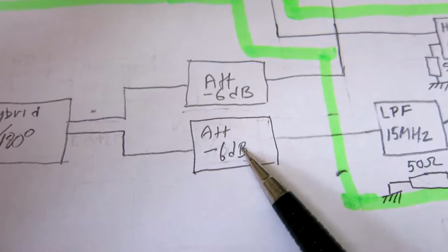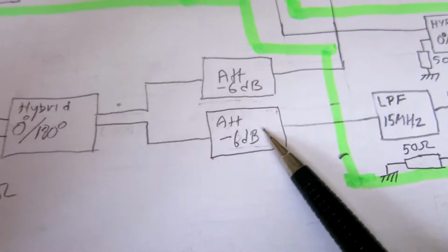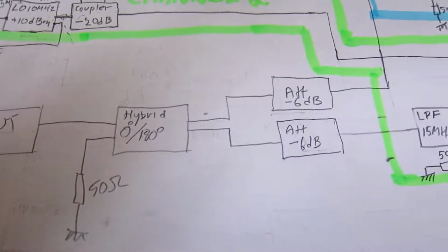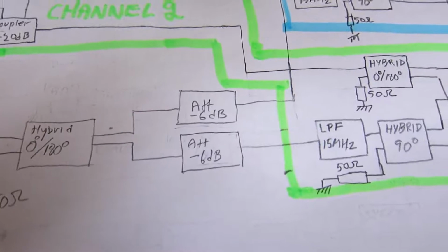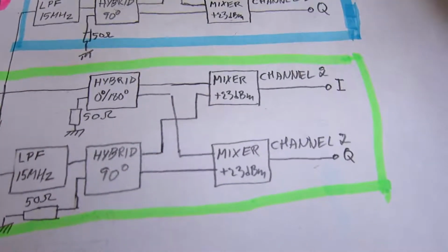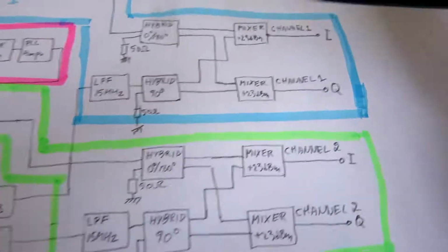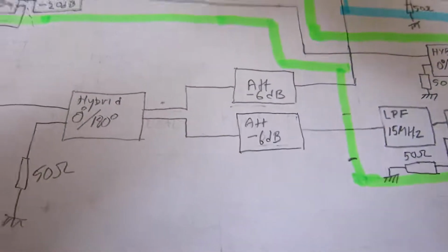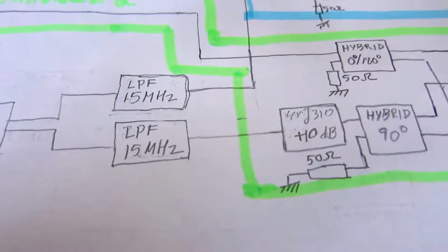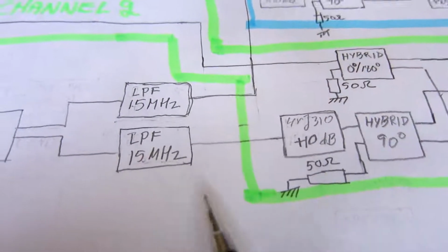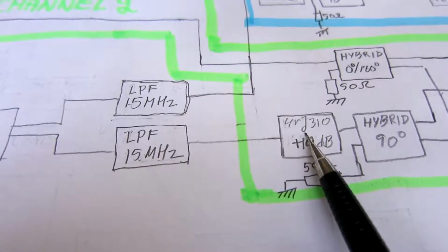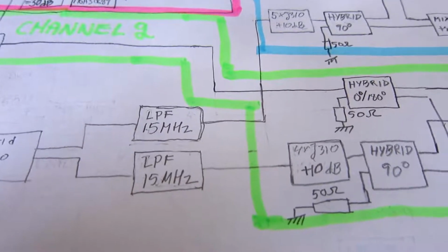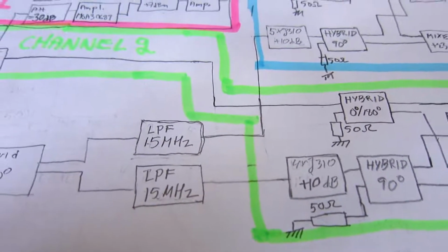There were two 6 decibel attenuators to set a suitable signal level for testing the Wenzel oscillator and not saturating the Schottky mixers. They were the limiting factors for the amplitude here. So I replaced these attenuators with low noise amplifiers and reversed the order between the low-pass filter and the amplifier. This has increased the level by something like 16 decibels.